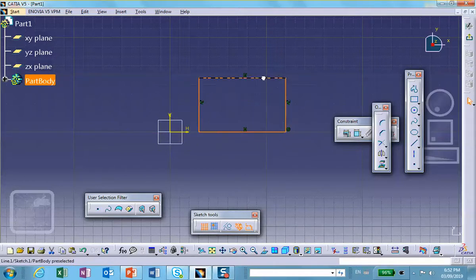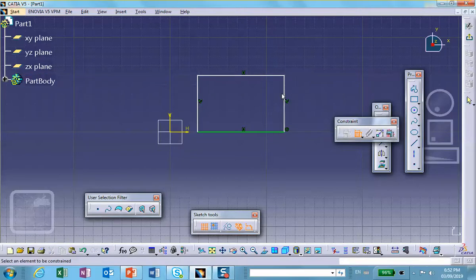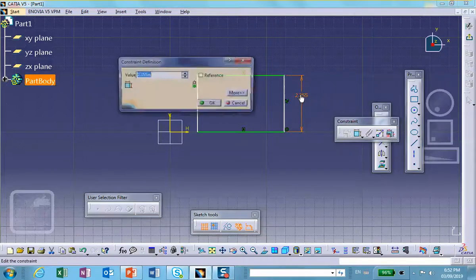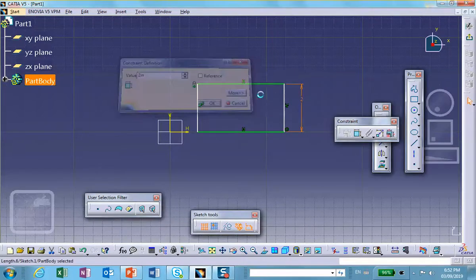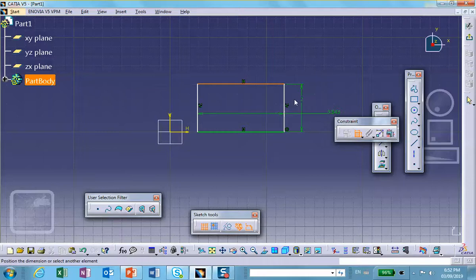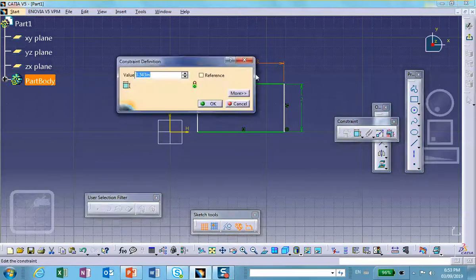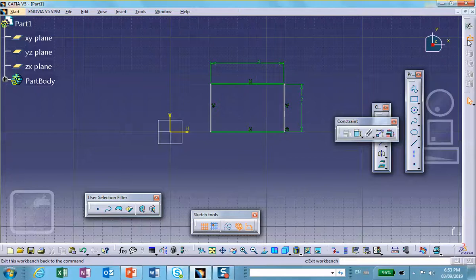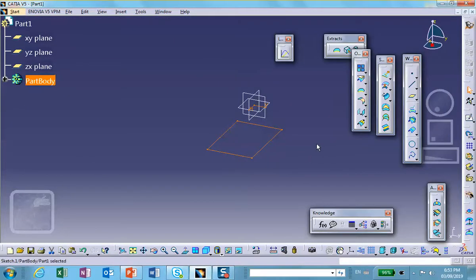Okay, the actual size of it is irrelevant, but I would like to always have an idea of how big these things are. So let's see now. This is roughly 2 inches. Okay, so let me make this thing 2, and obviously this is going to be around 4. So I'll make it about 3. Okay, good. Exit. Now I will be dealing with shell mesh a lot in this particular tour.